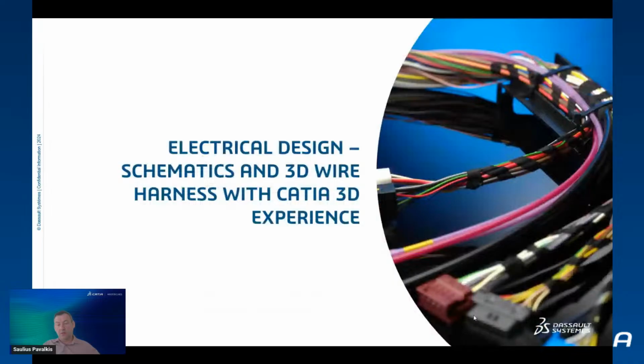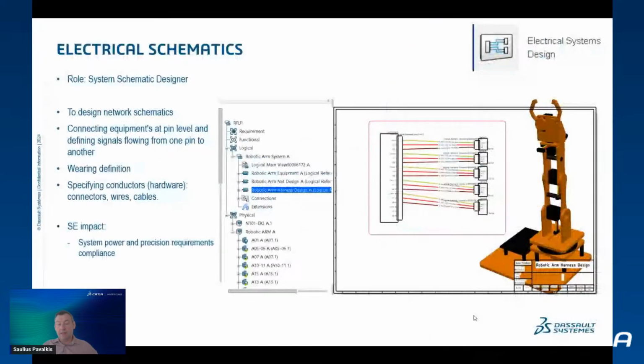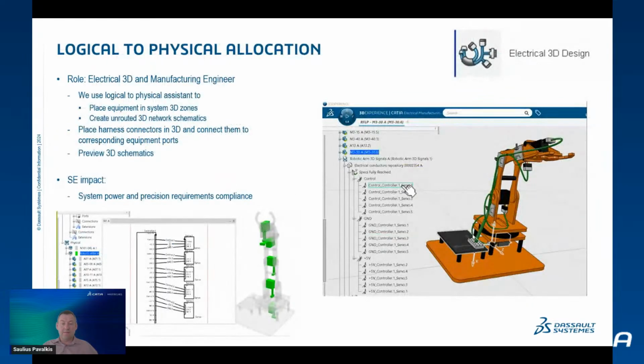And then we go to the electrical design, and we start doing schematics using libraries. So here you see the schematics: controller, 5 servo motors, gauges already here, connectors. And then we allocate electrical parts to 3D in order to perform so-called electrifying CAD. This is a big deal, because then you have full understanding of where your wires are going.